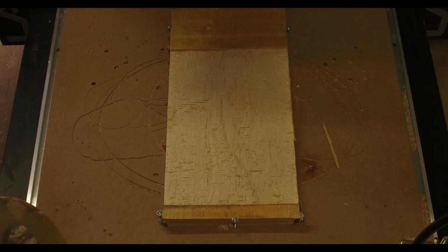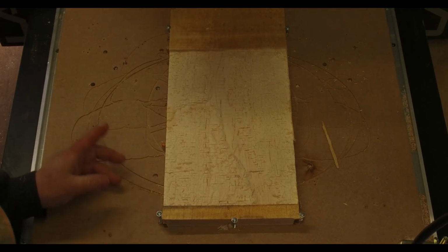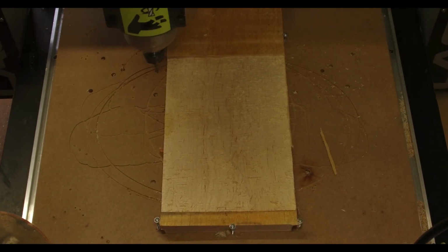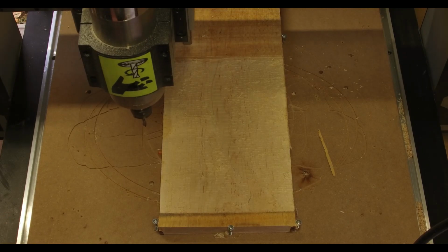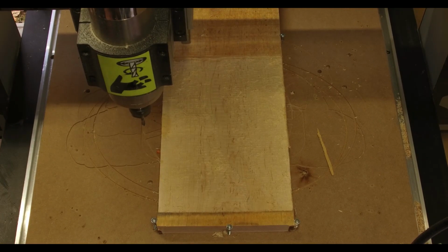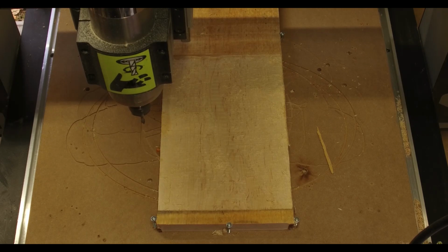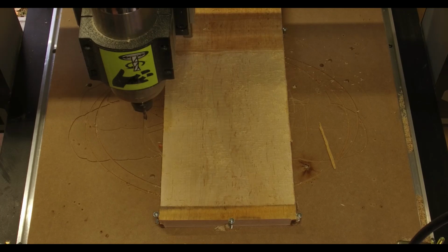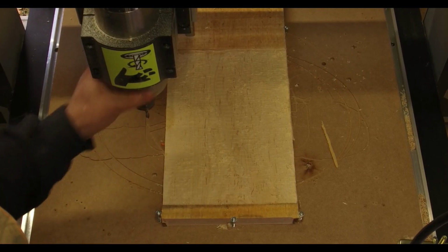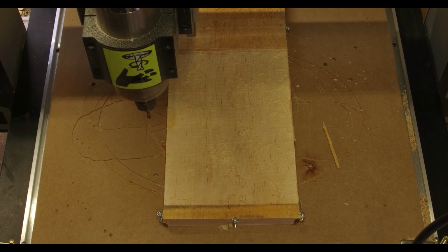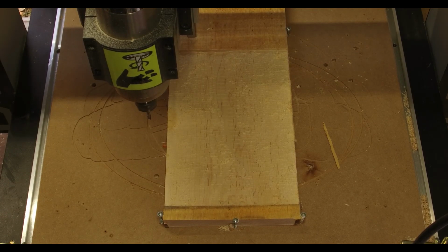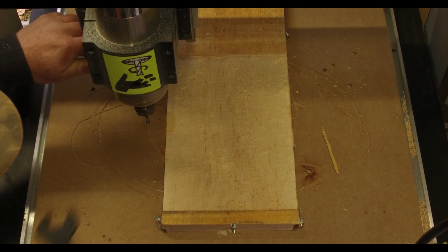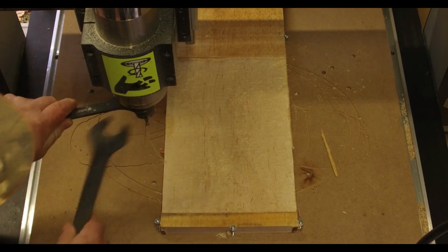So we got the majority of the bulk hogged off at the bigger mill. We're going to go now to 16th tapered ball nose. I know you don't need to rough off the majority with a tapered ball nose, but it just makes for less mess, because I don't really like running dust collection because it makes a lot of noise, and I don't like that. So we're going to go ahead here, put 16th inch tapered ball nose on, and we'll start the finish pass.